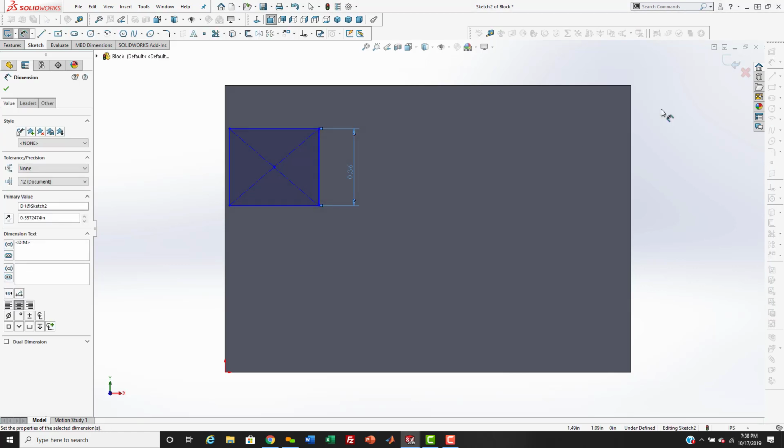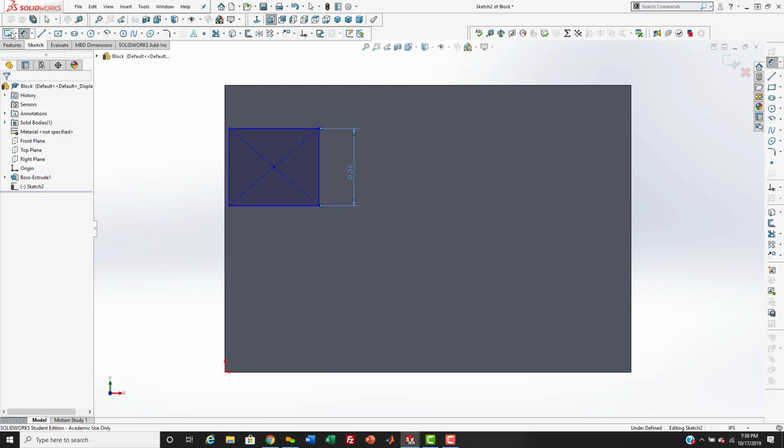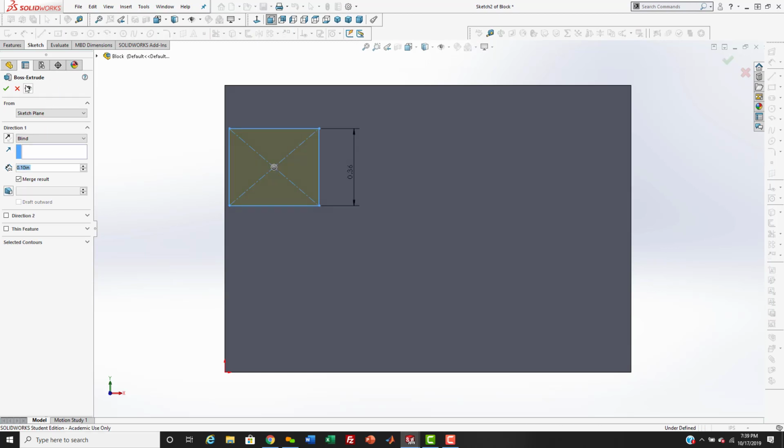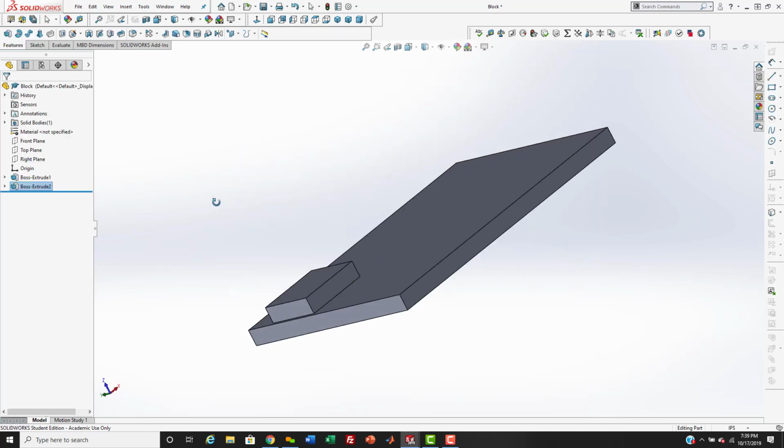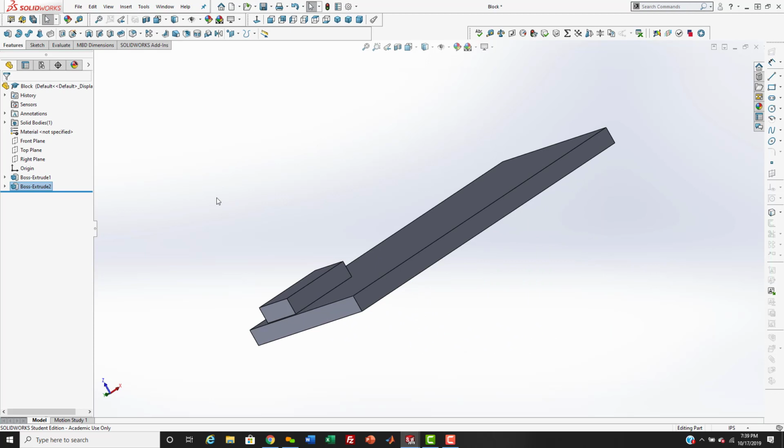Now, when you're done drawing, the book tells you close this, close that, and then hit that. But once you're finished, just close the sketch over here, and it'll automatically bring up the dialog for the extrusion. Make it the height you want, and hit OK. I mean, that's a quick step. A quick way to remove some of the steps that the book lists.